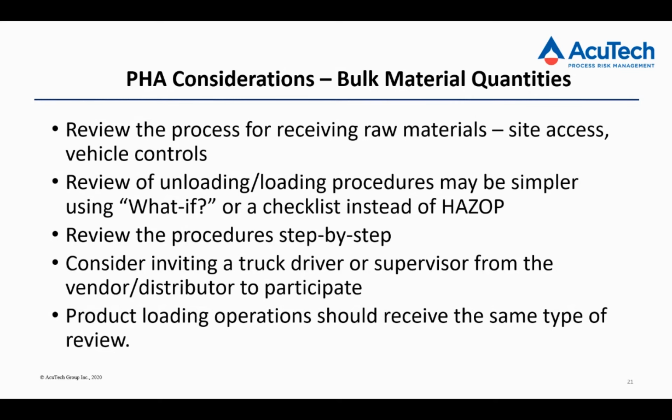So some things to think about. Review the unloading process really from beginning to end. And that includes the truck arrives at the site. How do you verify it's the right material? Is there testing involved? Are there certificates of analysis that need to be examined, and by who? And then who directs that driver to the unloading spot?